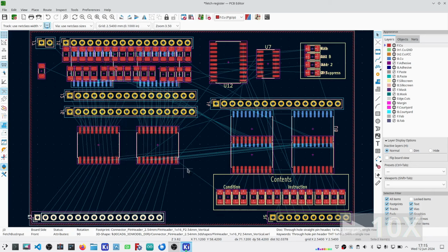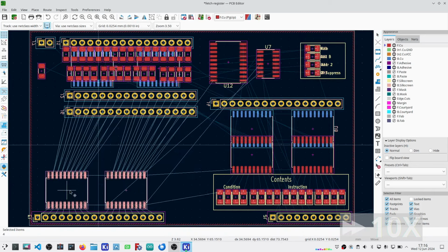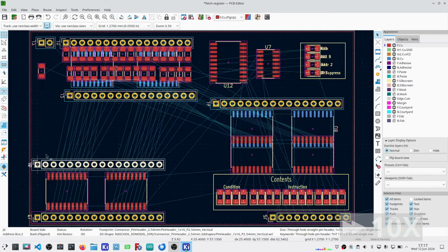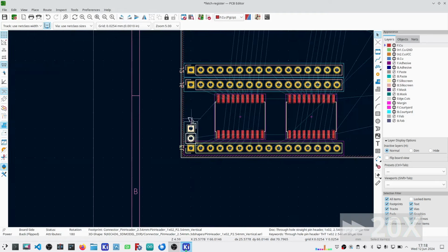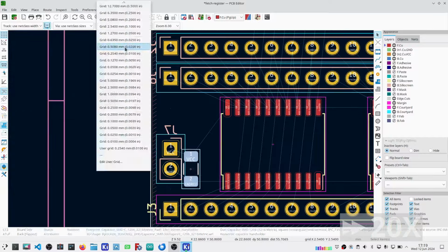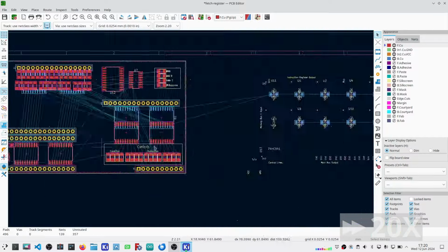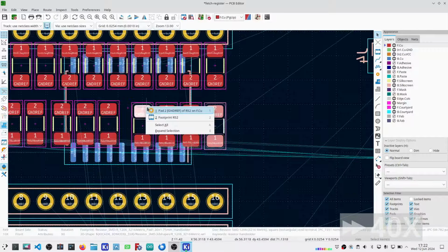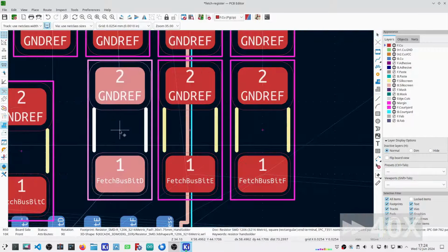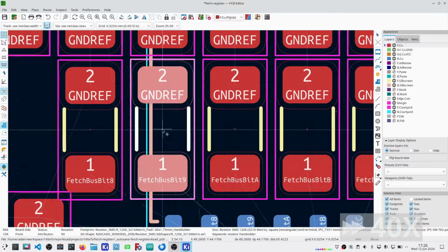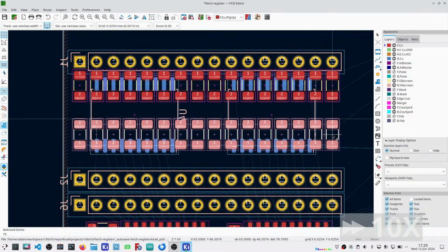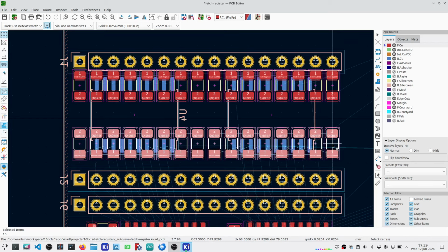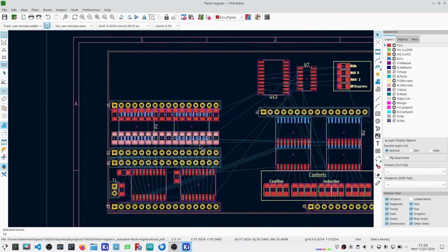First order of business here is I want to try to collapse this left side of the board here. I believe I've got lots of opportunity to do that. I need to squeeze two capacitors in there. Okay, now let me move this down and get it lined up properly. Okay, now those are going to be too close together, so let's stretch those out just a little bit. Yeah, I think that'll work. And that's as dense as I can get that section. So I'm pleased with that.